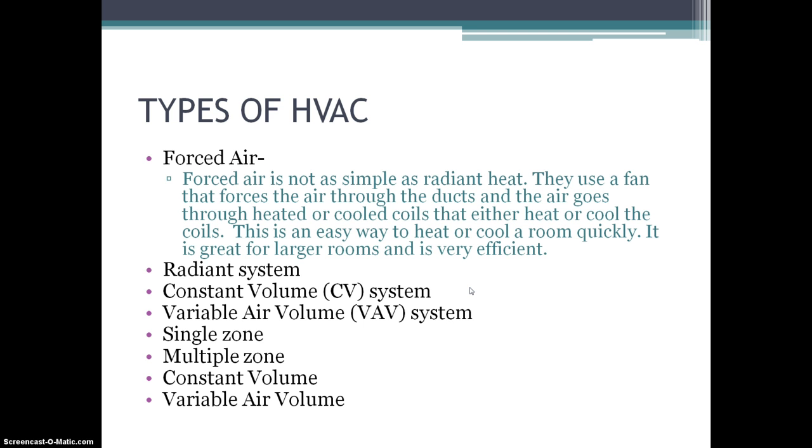So if your room's too cold, then it will kick on and cycle the air through the cold air return, and then it goes around a chamber which is full of air. Then after it's cycled through the blower, after it's been on a while, it will turn off after it's reached the right temperature.